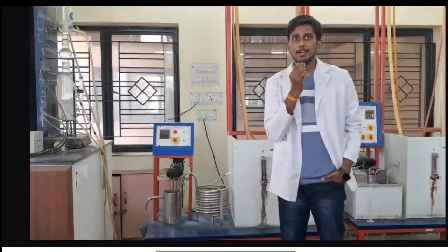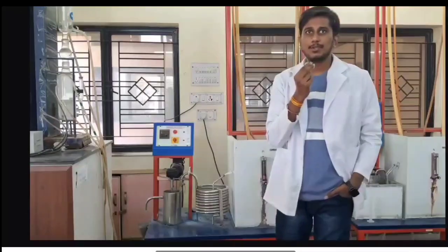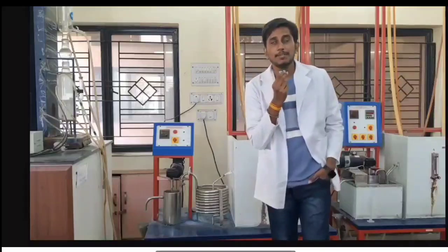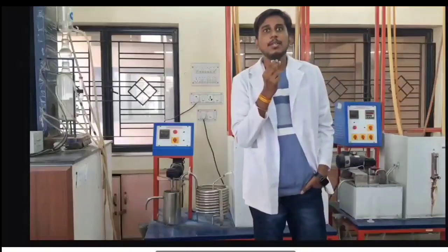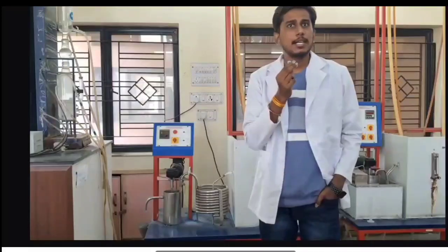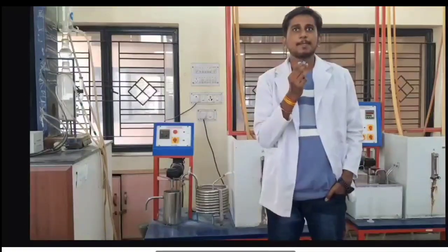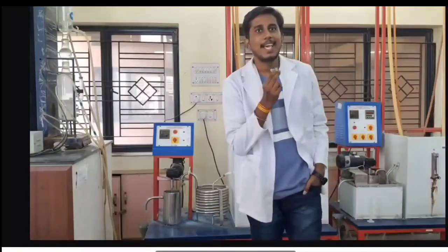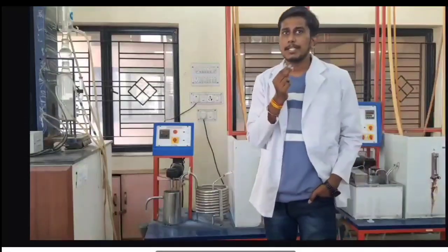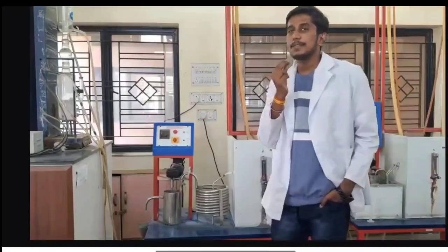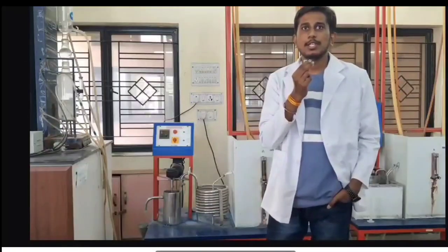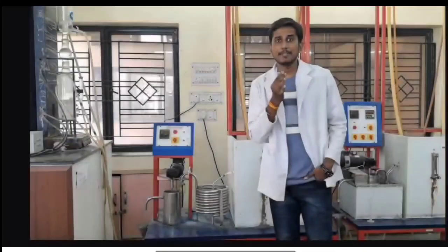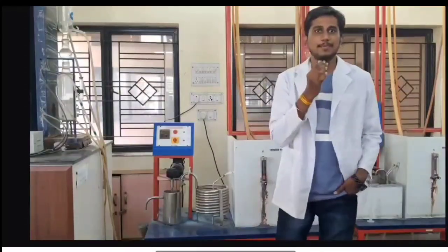The next part is preparing the standard solutions for the titration. For the next part of our experiment, we need two standard solutions, 0.1 normal HCl and 0.1 normal NaOH. These will be used in the titration step to determine the conversion rate of the reactor. Normality is a way to express concentration that accounts for reactive capacity. For instance, 0.1 normal HCl has 0.1 equivalent of HCl per liter. Using the formula N1V1 = N2V2, we dilute the concentrated stock solution to the desired 0.1 normal. Similarly, we can prepare the NaOH solution also.